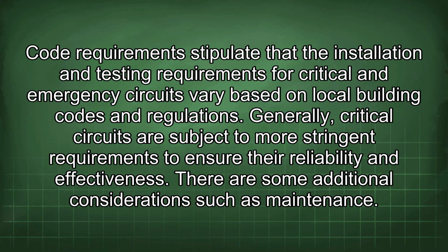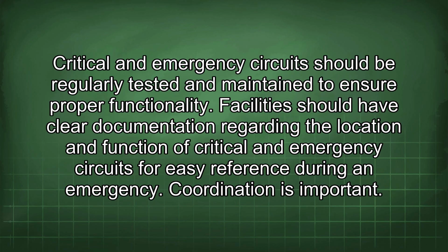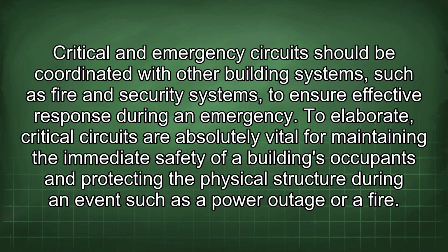There are some additional considerations, such as maintenance. Critical and emergency circuits should be regularly tested and maintained to ensure proper functionality. Facilities should have clear documentation regarding the location and function of critical and emergency circuits for easy reference during an emergency. Coordination is important. Critical and emergency circuits should be coordinated with other building systems such as fire and security systems to ensure effective response during an emergency.